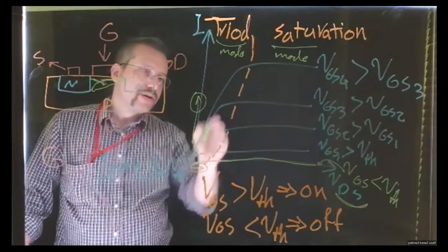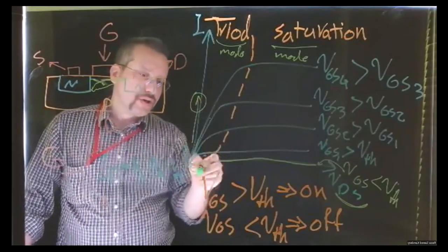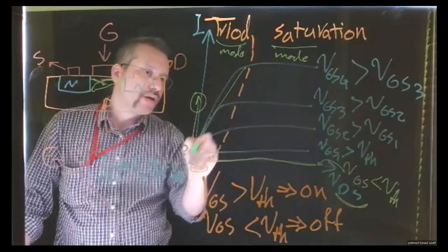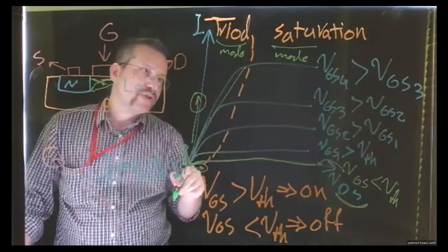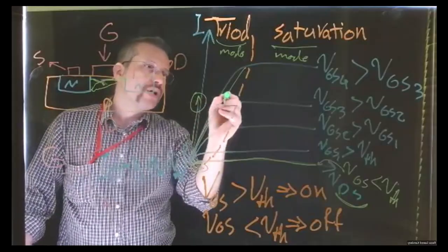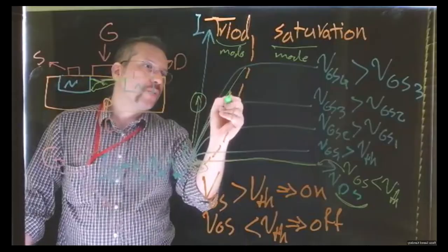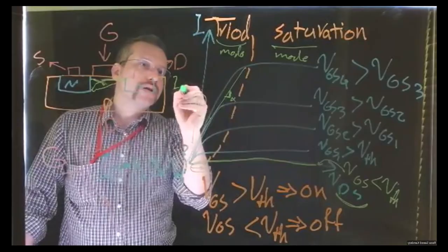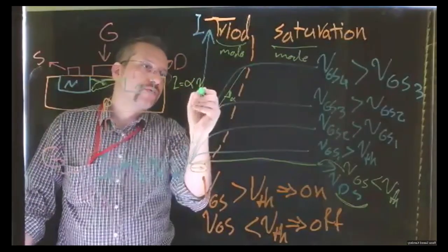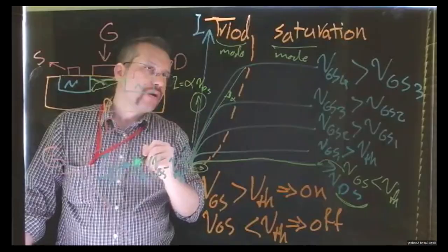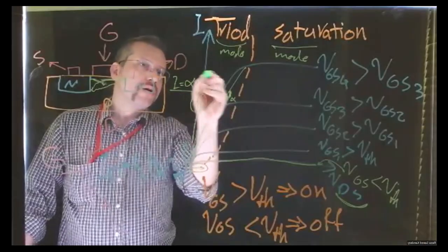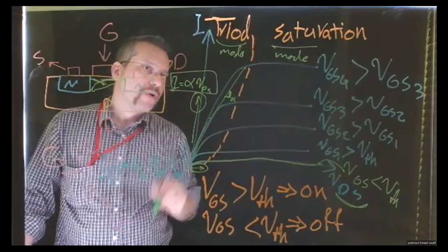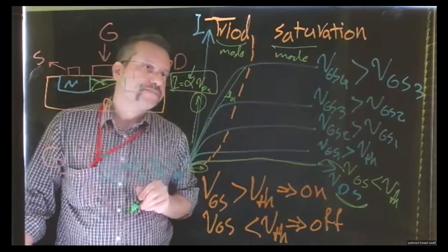It's very simple: if you approximate that curve with a simple line, with a slope of alpha, then your current is equal to alpha times the voltage VDS. So it works as an amplifier with the gain of alpha.